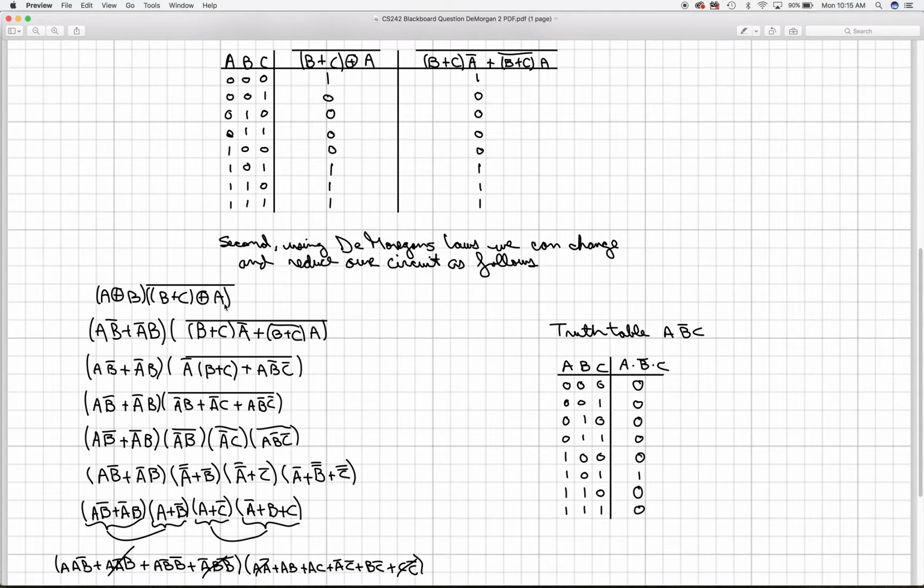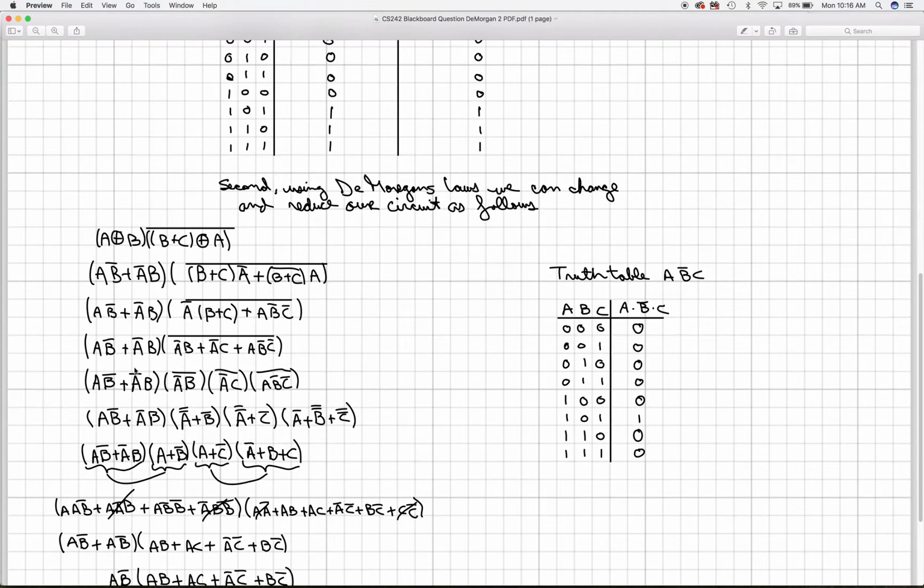Well, the first thing that I'm going to need to do is to remove that exclusive OR and this exclusive OR. Well, A exclusive OR B is the same thing as A B NOT or B NOT A. We've already decided what this is going to be. That's this part over here. It's really going to be the same thing as this, so you'll see that I've just rewritten the B or C A NOT, the B or C NOT A, and then of course the whole thing is NOTed. All right, so let's leave this part alone. That's why you see I've just simply rewritten this.